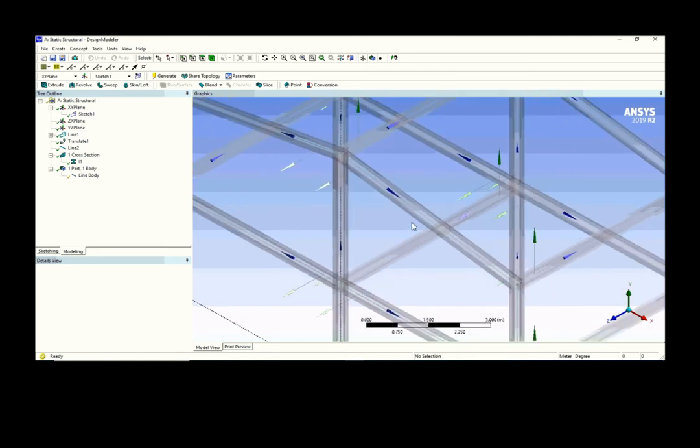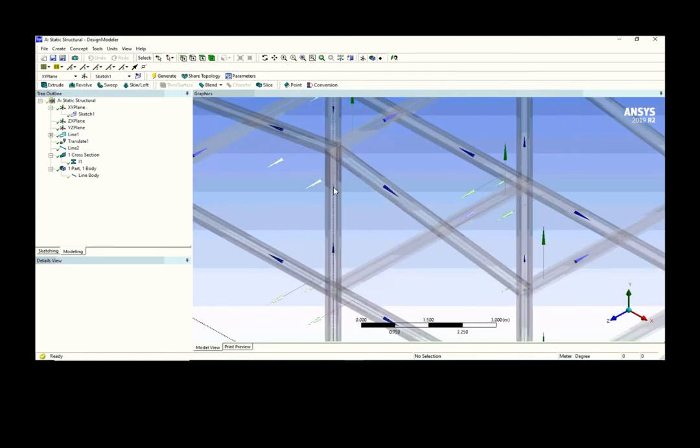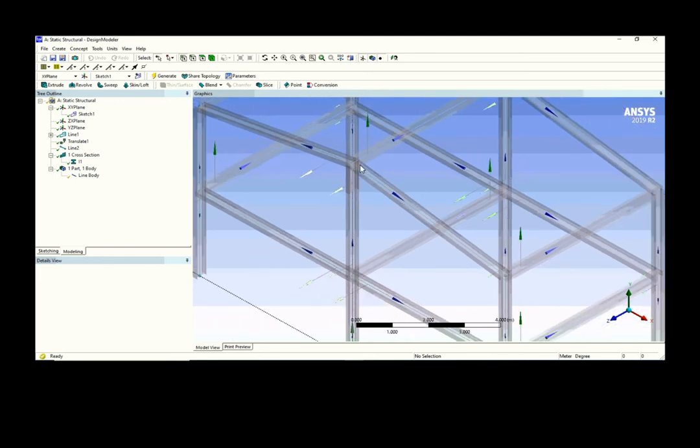They are actually in H beam orientation, right? It's not really an I beam. If you put it like this, it won't take too much load. It bends a lot because it's not strong enough in this direction. So you have to orient it into the correct direction.